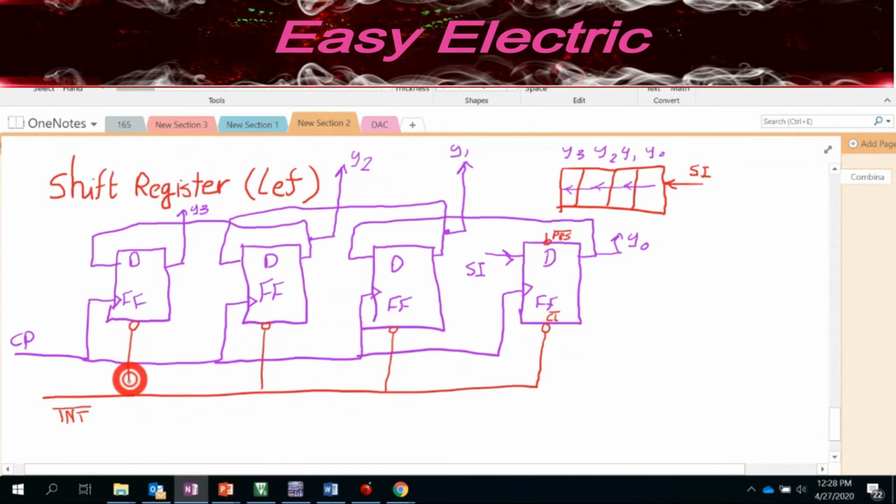clear pins, okay? So whenever you want to start to work with this shift register, you just activate this for a short time. That means you initialize with all 0, then it starts to do its own job. For a short time you just activate it, then it's deactivated. For the preset, we just connect them to the VCC because we are not going to use them, just deactivate them. That's the reason I connect all of them to the VCC. They do nothing in this design, okay?